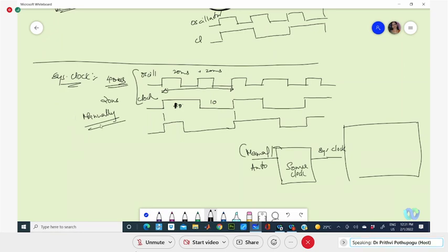if your design is in auto mode, even if it senses any manual interruption of the button, it should not truncate the auto mode in between. It should complete one full iteration. And whenever there is a release of the manual operation, it should automatically switch over to the auto mode.